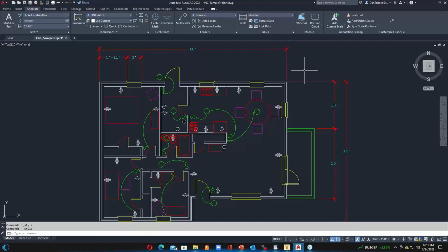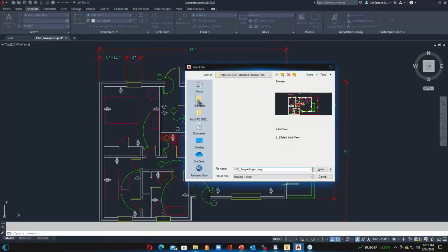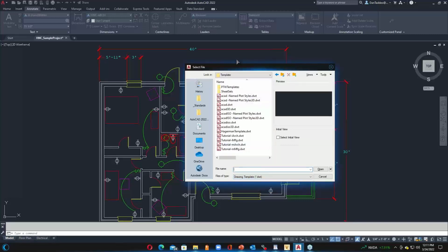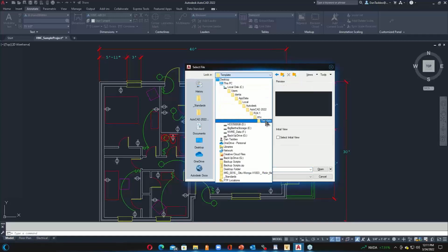That's where we get into managing our standards using things like templates. If I were to open up my CAD templates, you'll notice that I'm using a standard directory with all these different folders in place, and I have one that's called templates. Here's my standard template, that's either a DWT, or I can change the property filter to show me a DWG, which will hop over to a directory that's configured within AutoCAD as the default template directory.